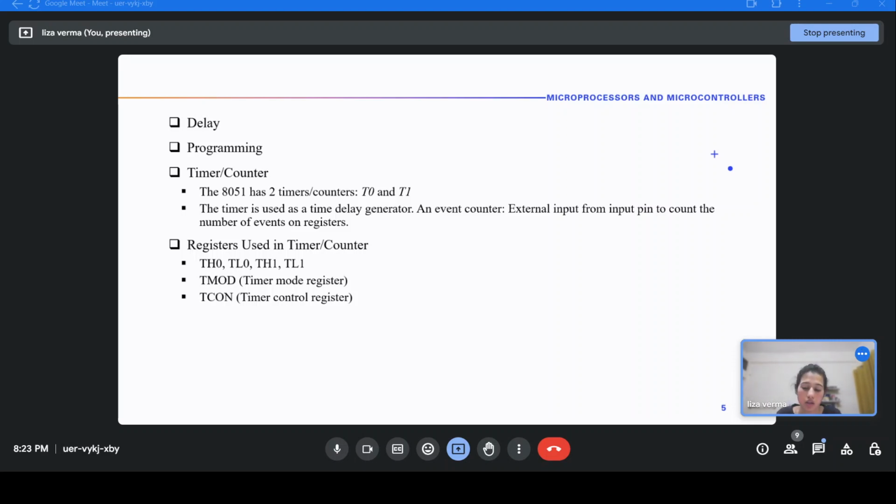Remember, you write NOP, put it in a loop, and while the loop counter doesn't go to 0, the NOP instruction will keep the MPU busy in implementing the NOP instructions in that loop. So, to relieve the processor during the delay, this timer is used.